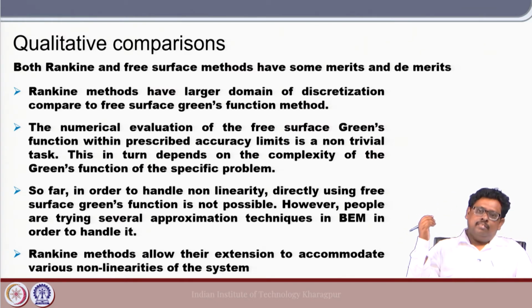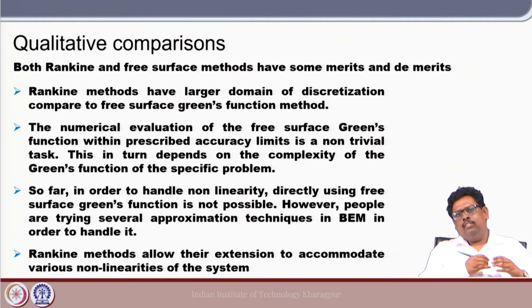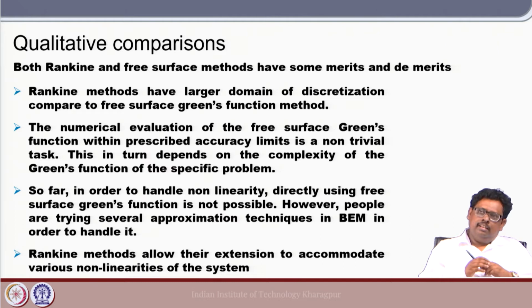Okay. So, therefore, in a way it is better to say that if you are interested in linear analysis, and you know how to write the complicated free surface Green's function, then we very popularly call it the Wamit type solution, right.